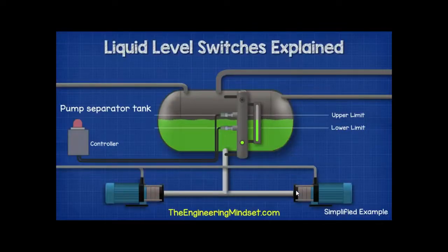Coming back to the column installation, we could face the problem that the liquid level drops. In this case, the liquid level is going to come below a lower limit switch. The sensor will detect that phase change from a liquid to a vapor and will send a warning signal to the system controller. Additionally, we could face the issue of overfill, where the liquid becomes too high in the vessel. This means the liquid refrigerant will rise above the upper sensor. The sensor will also detect there has been a phase change from vapor to liquid and will again send a warning signal to the system controller. In either case, the switch activates an inbuilt relay which is used to sound an alarm and can be connected to the system PLC or programmable logic controller.